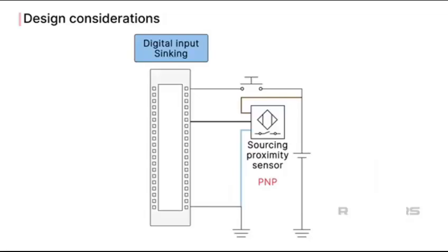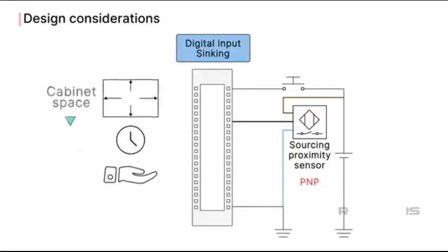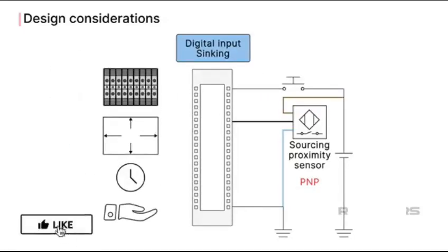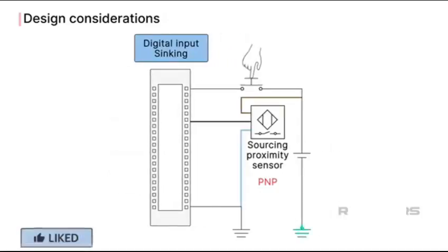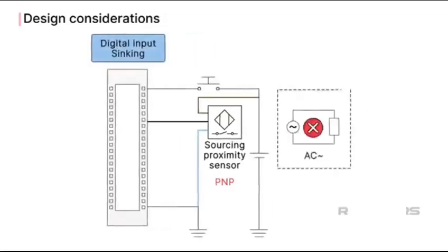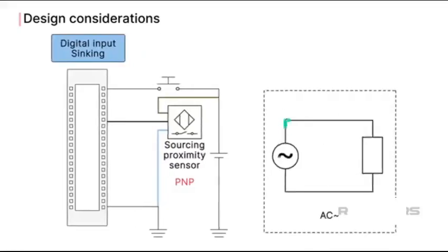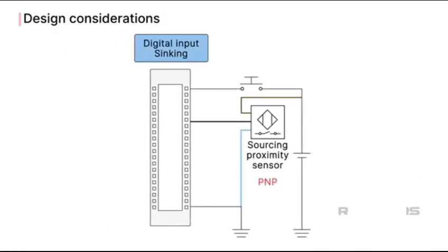Good design habits require wiring all I/O points with the shared common to either source or sink. This will save time, cabinet space, and terminal blocks. How so? If you wire the circuit as a block, the common can be shared and supply more than one sensor. Note that we have been discussing 3-wire sensor circuits and not AC-powered circuits. AC changes polarity naturally. DC uses transistors. Do not use an AC power supply to source a DC source sink point. Why? DC and AC do not match, and instruments will fault.